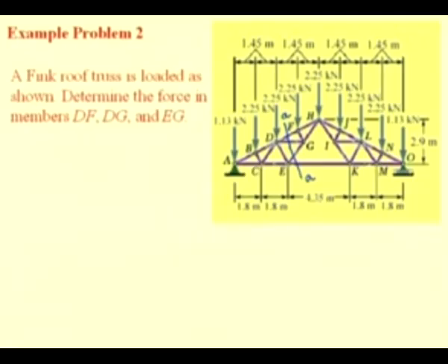So, now we have to see how we can determine one of the unknowns. Say the force in this member EK has to be determined. In order to determine this, we can consider another section, say BB, which passes through HJ and this member and this member EK.